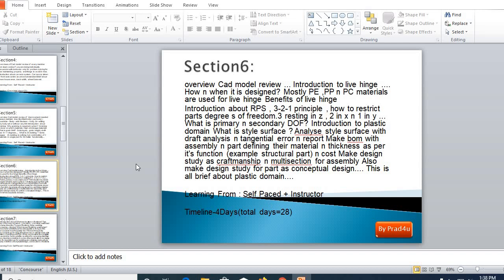Every mechanical product design engineer in the automotive plastic domain is working with some styling surface, that is the A class surface, and we have to work on that A class surface to make it solid or thick with the class B surface, and close all these surfaces with a surface called the C class surface. These three surfaces make a closed body for that part.